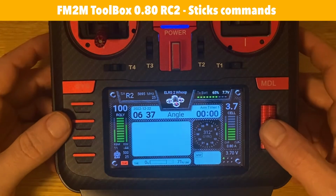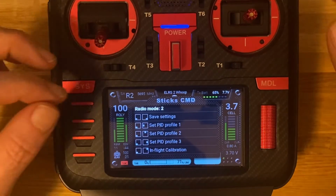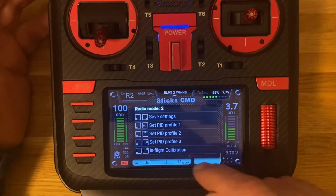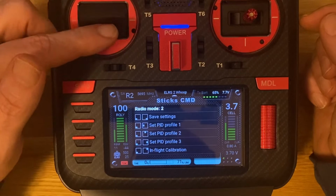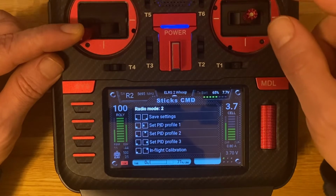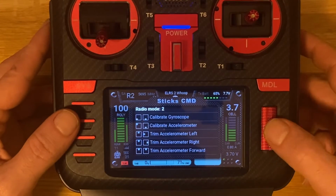Alright, so there's another module here. It's called Sticks Commands. You can see that when the craft is disarmed, you can issue stick commands. For example, I'm using it a lot for changing PID profile through the sticks. I have my radio in mode 2. So to set the PID, I have to put the left stick in the bottom left position, and then if I go left, it's PID profile 1, PID profile 2, PID profile 3. So I can see this scrolling, of course, through